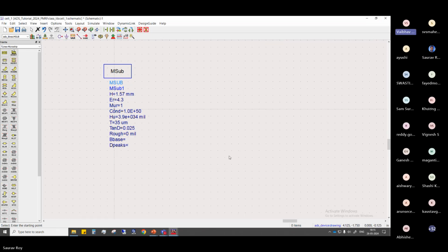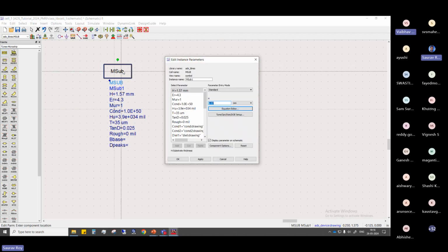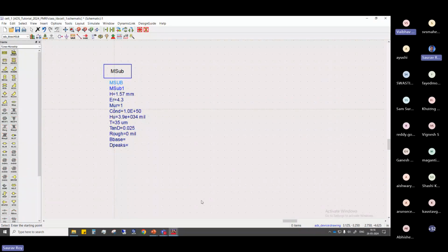Sir, when you created this workspace, you first asked us to select the mil resolution, and later we change the units from mil to millimeters. Instead, if we directly select the resolution in millimeters, there would be no need to change the dimensions from mil to millimeter, isn't it? No. That is just the underlying method required. But once you take these components, they are completely different. You have to define the units here, whatever you take outside does not matter. Here you see all the defined units are there. You have to select this separately. Yes, because I faced that problem. I started a design with the mil resolution, then forgot to change the dimension, so I got wrong simulations. Okay, it's fine. Thank you, sir. Yeah. Next. Yes, hello.